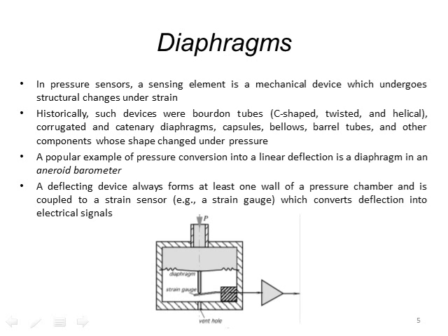And when you get an increase in pressure P, but you do not get an increase in pressure on the lower white area of the vessel, then this diaphragm will bend downwards because you get a net force per unit area pushing on this diaphragm. And then as the diaphragm pushes down, it creates more strain in the strain sensor. Therefore, you change the electrical resistance, you get a current change, and then you can measure the current change via the amplifier that's shown.